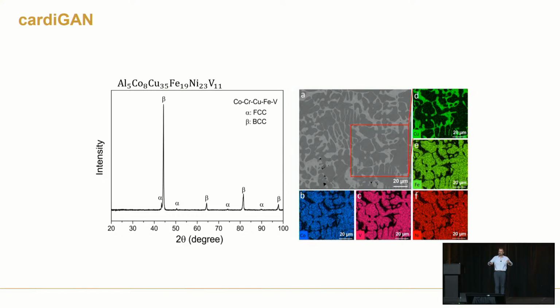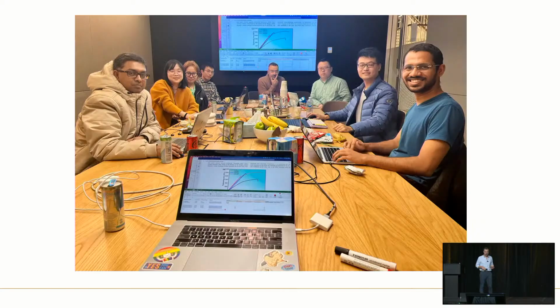And we thought, let's do the SEM and we'll just see a single phase FCC alloy. It turns out actually that nature is often quite funny and one step ahead. This particular alloy that we made has 2 phases, both of which are FCC, which the model was unable to predict. And that's very rare to see in high entropy alloys.